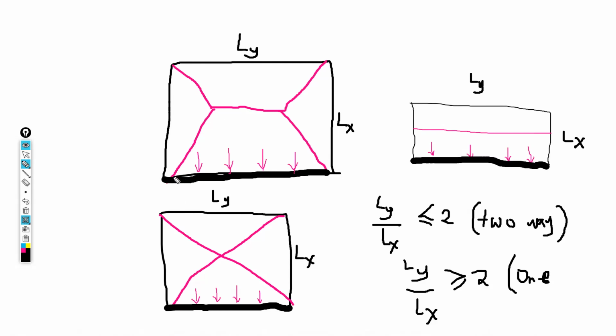For you to compute, if you have to do it from first principles, the magnitude of load from this slab onto this beam, you're going to get this tributary area, get the area of this trapezium, then multiply it by the imposed load. Say our imposed load for this slab is 4, get the area of this trapezium, multiply it by 4. That is the load that is going to be carried onto this beam, okay?